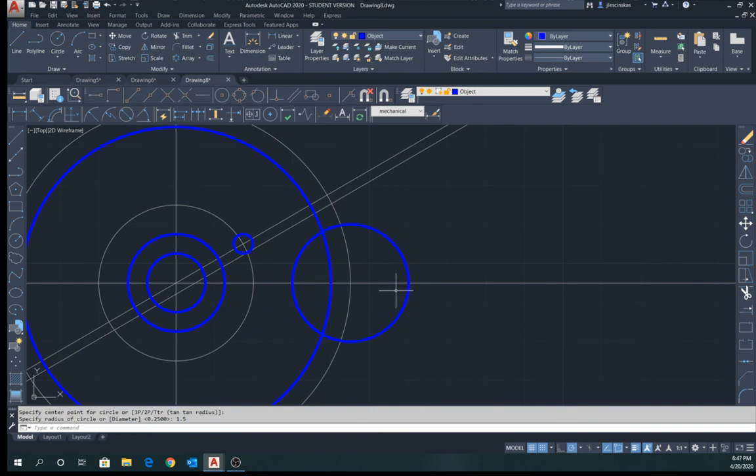And you're probably wondering what the heck we're doing here and how we're going to turn this into this Geneva cam. Well, what we're doing is we're going to utilize two properties of AutoCAD. One is the mirror function, and the other is the array function. And the final step that we need before we start doing lots of trims is to simply add a line which will go from the intersection of this circle out to the intersection of that circle.